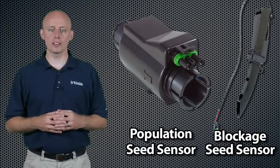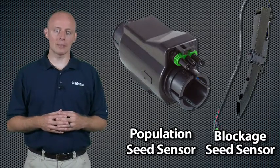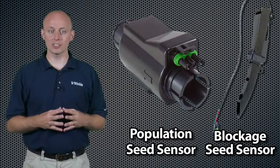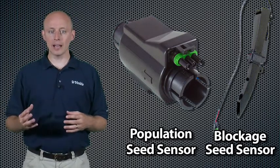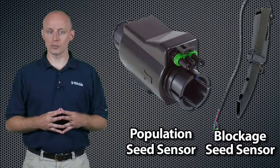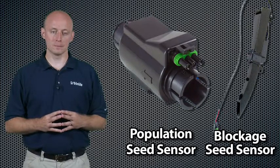Another important sensor for True Application is seeding sensors. These sensors monitor seed from the planter that is going into the ground. And there are two types of seed sensors: population and blockage. A population seed sensor counts the seeds or the rate at which the seeds are being planted. The blockage seed sensor simply detects if seeds are flowing or not. Both of these sensors provide feedback in the flow and application system.